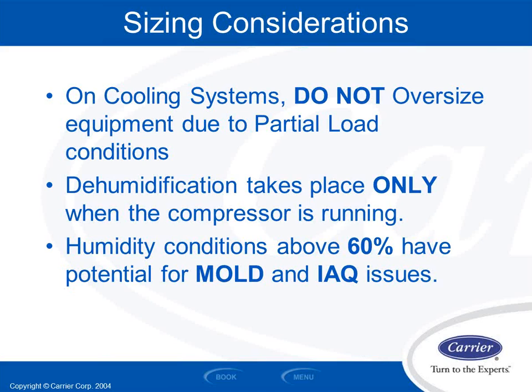And then if you have spaces that have lots of humidity generation, meaning that you have a locker room with showers, or you have a workout fitness center, or you have some kind of lobby with a bunch of water fixtures and fountains and stuff in it, you're generating all this moisture. In those cases, you're going to need specialized equipment that has the ability to subcool and then reheat that air back up to a comfortable temperature, right? So like hot gas reheat or a humidizer or something of that nature.